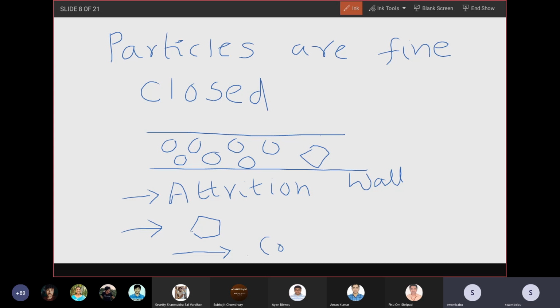If the materials tend to be cohesive, that is, sticking to each other, there is a chance of blockage. If the particles are cohesive, they tend to interact and join together and can form big agglomerates, and those agglomerates can cause the blockage of the pipeline.